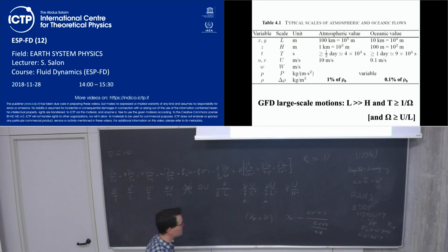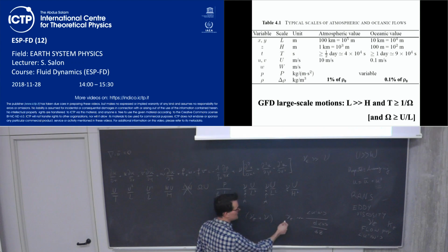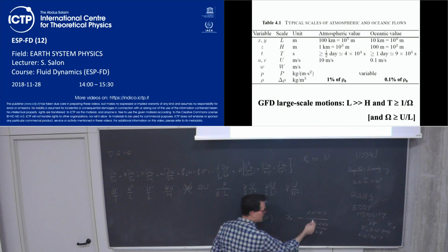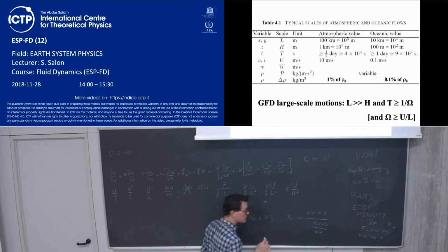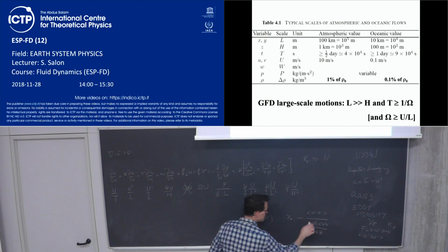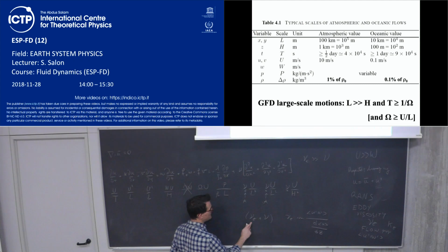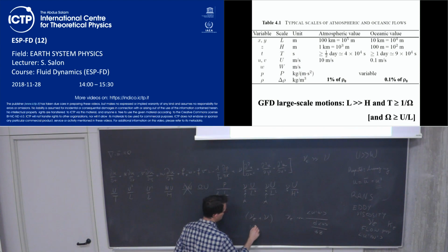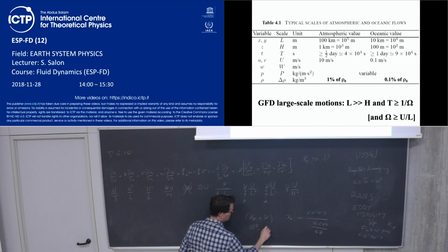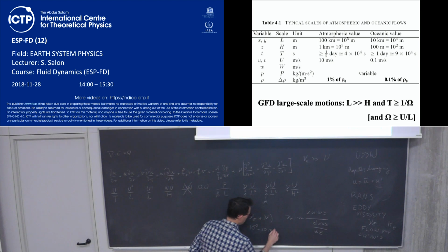And if we take measurements, I mean, if we are able to measure, which is not very easy, as I told you, these two components, and we calculate this, we will have that the eddy viscosity has values from about 10 to the minus 2, can be even 10 meters squared per second.